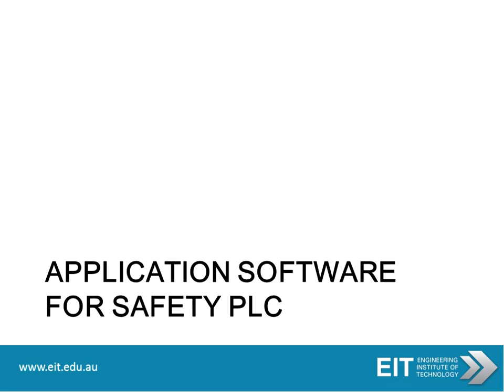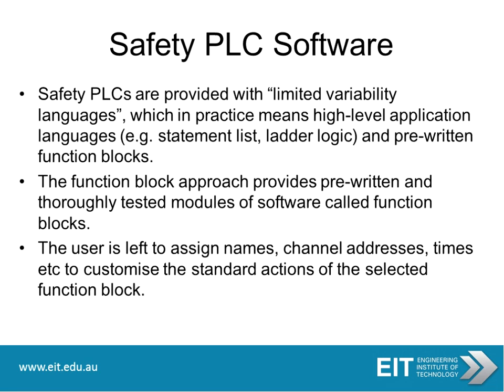Then if you look at application software for your safety PLCs, they're provided with limited variability languages, which in practice means high-level application languages, like statement list, ladder logic, and pre-written function blocks. Now, the function block approach provides pre-written and thoroughly tested modules of software called function blocks. And the user is left to assign names, channel addresses, times, etc. to customize the standard actions of the selected function block.